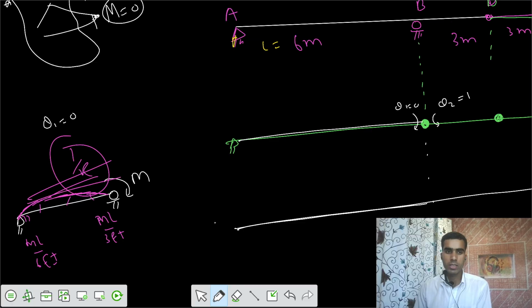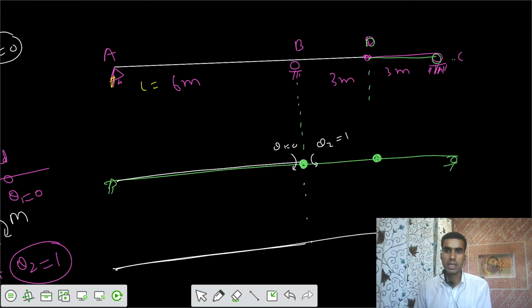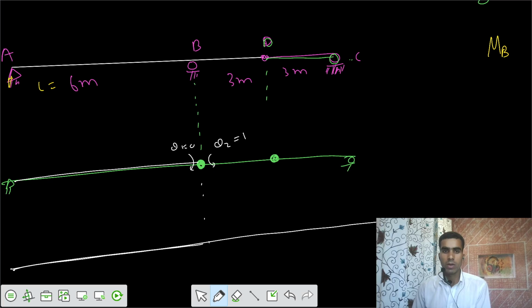So we say that for this part, even though this is a statically determinate beam, if there is curvature developed for the part, this part takes ILD of 0. That means theta 1 should be 0, such that theta 2 is entirely taken by the other part, BD. We can call that BD. Now we have two internal hinges. Let's say we have this hinge, and we have one more hinge. After that, we have support C.